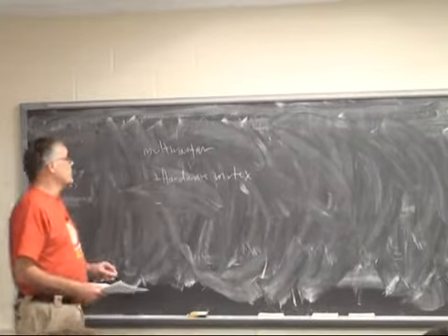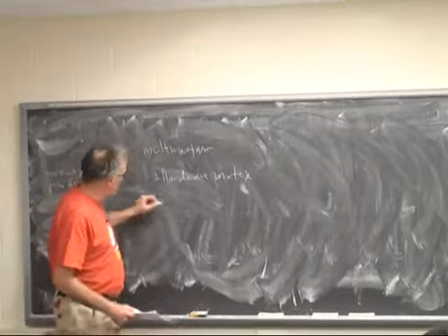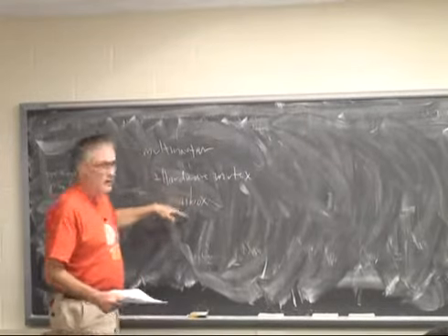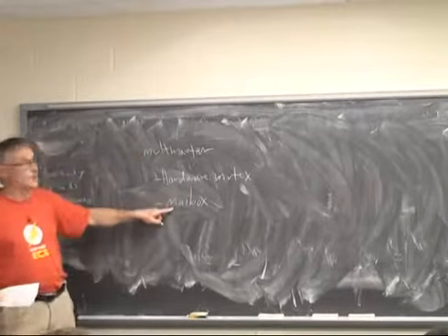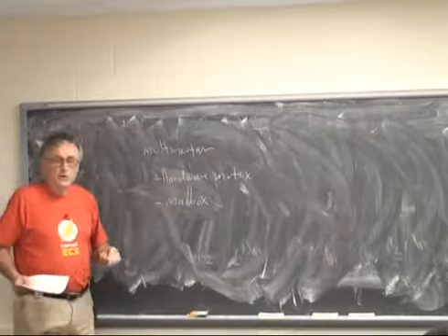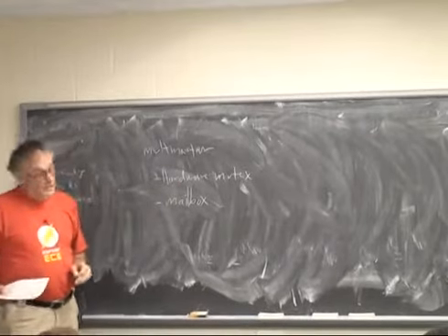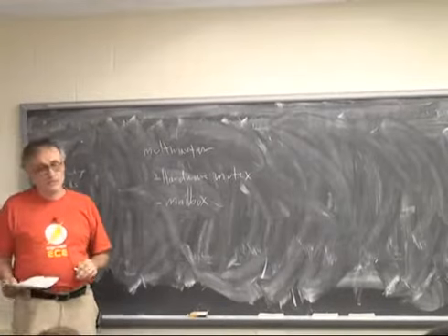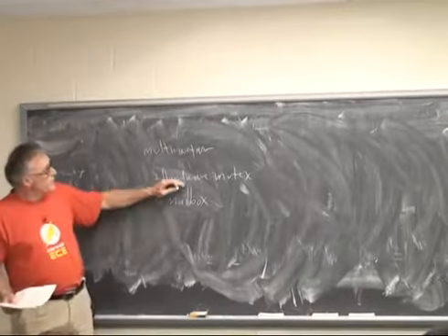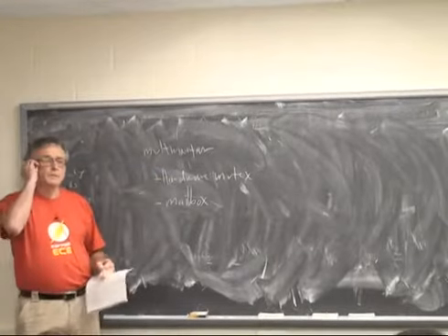And then the other construct which is available is a mailbox. And again, this is a hardware construct. It consists of a chunk of memory that you specify, either M4K block or SD-RAM or whatever it happens to be, that is shared between a couple of NIOS 2s.